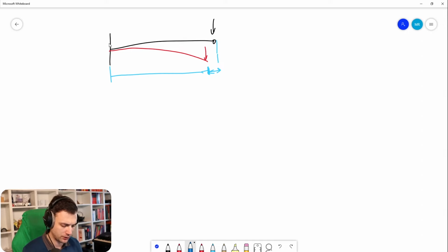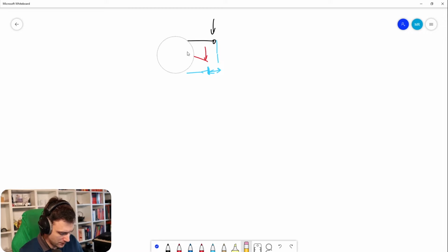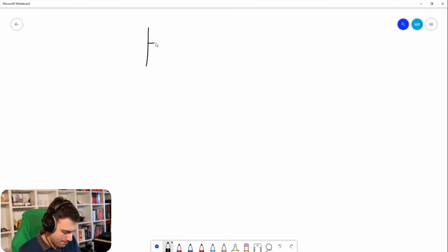So that's geometric nonlinearity. You can see that, for example, with a fishing rod, right? So it turns, you have large rotations. That's usually a sign when to include nonlinearity in a geometric context. It's with large rotations. That's one thing to consider.